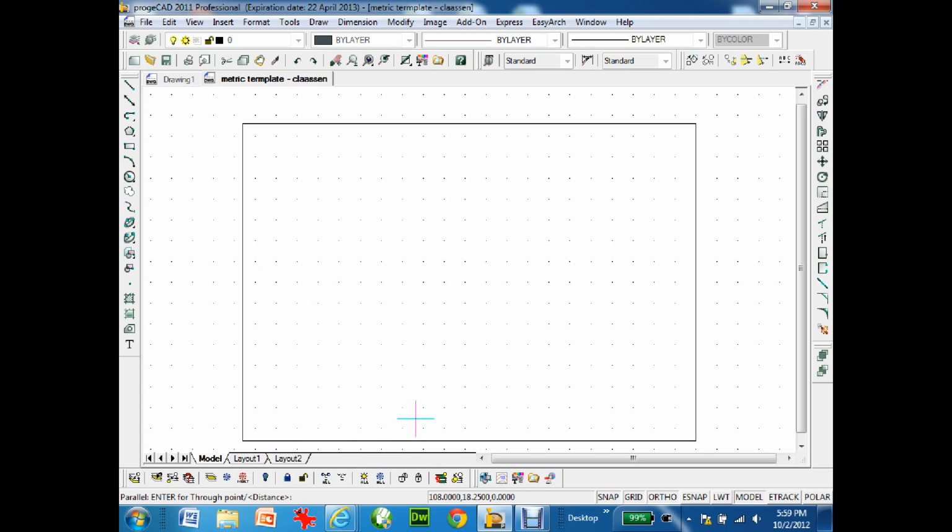Now that I've done that, I'm going to offset the bottom line, so I type in offset, and now it says the distance, and I know from the assignment I'm supposed to offset it by 20 millimeters. So I'll type 20 millimeters, grab the object or the entity, click it, and as long as I click anywhere up here, it will go this way. There it is. Okay, I'm going to hit escape to exit out of that command.